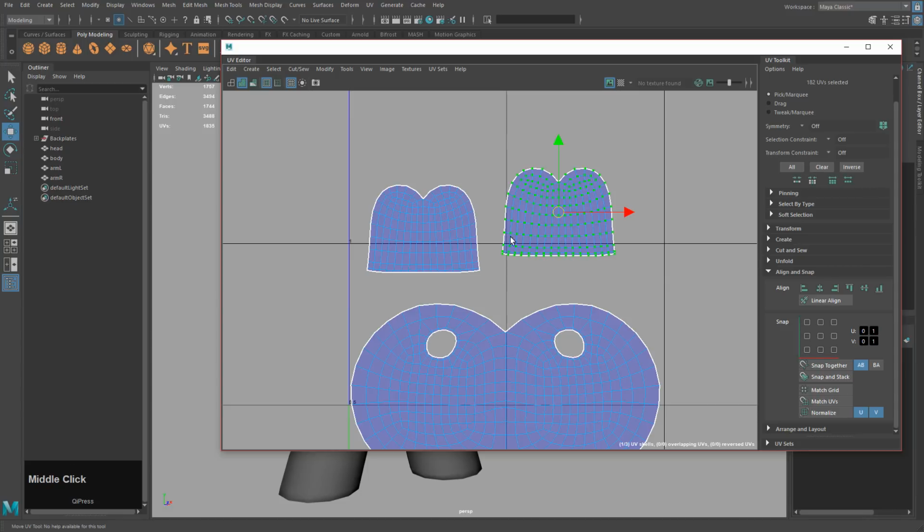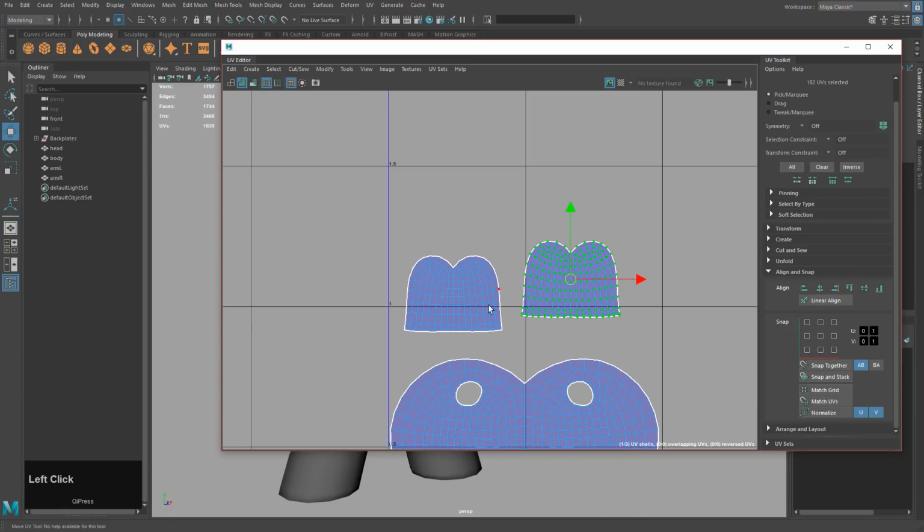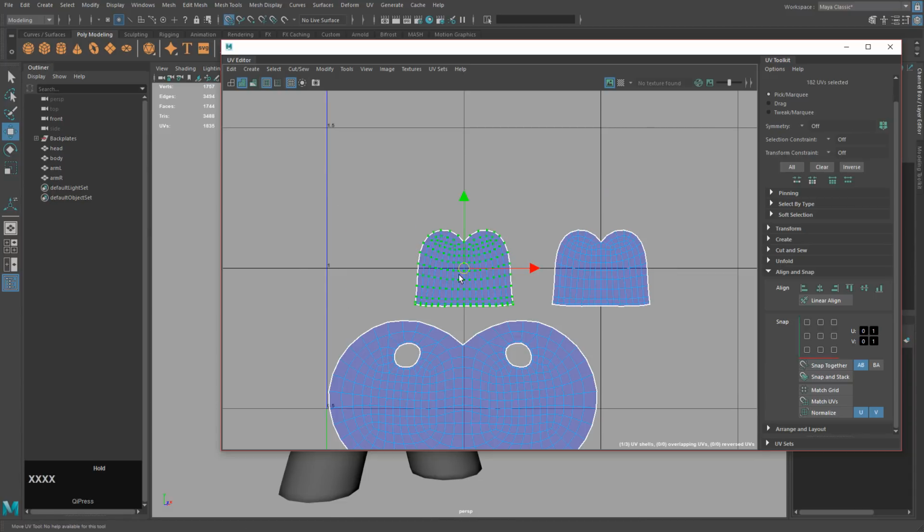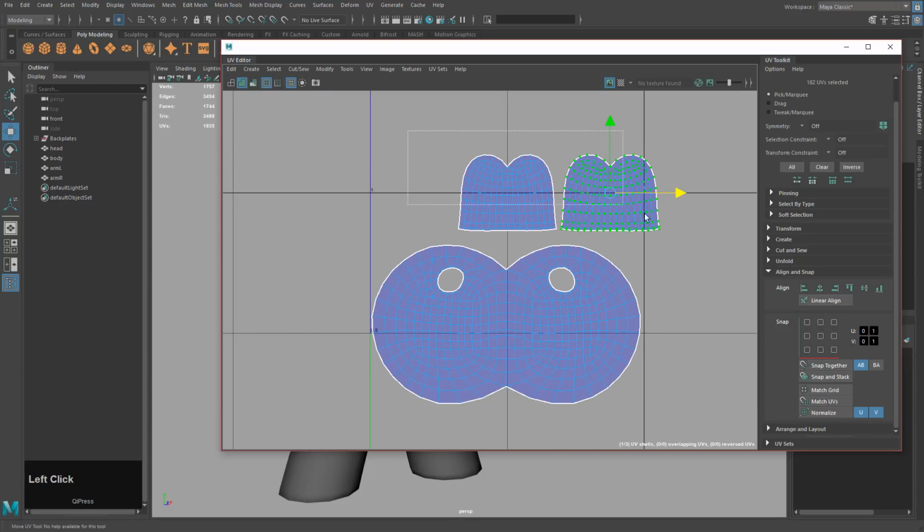And then I want to make sure everything's in the same plane, so that if, let's say, I paint this ear, I can flip it exactly to the other side to paint that ear. So I'm going to hold X, drag here, hold X on this selection, hold X, middle drag here. Now I know they're in the same line, and what holding X did is it snapped them to the grid. Now if I move them close together like this, just horizontally, I can then select both, hold X and snap here. So now I know they're both symmetrical.